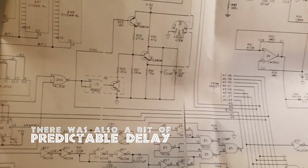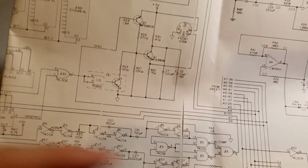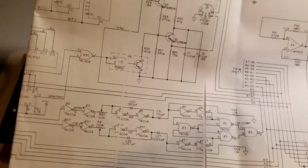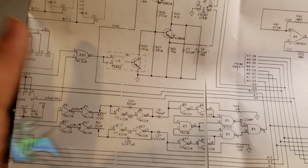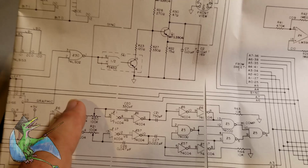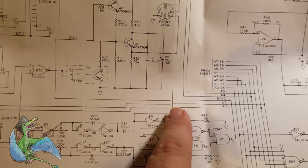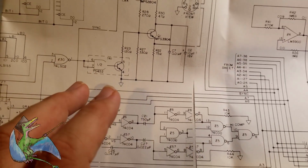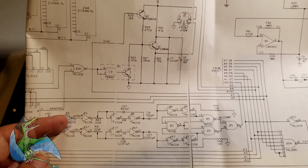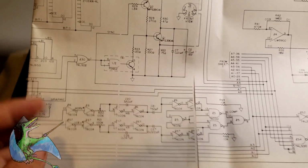We're in the horizontal blanking area. Sometime in here should happen a horizontal sync pulse. So this inverter actually does 3 different things, and even though it's a digital circuit, it actually behaves in an analog manner during parts of this, sort of.